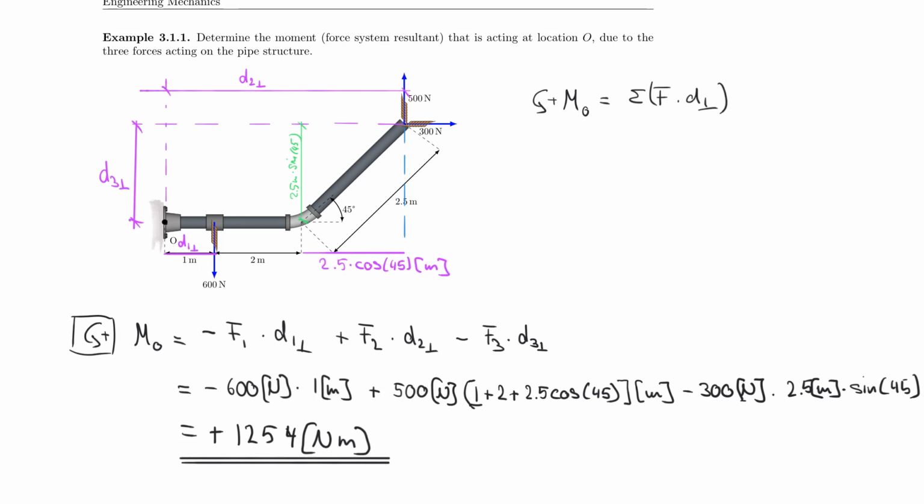And then also that we set plus here, because the plus tells us more than just it's a positive number. It also tells us that we're dealing with a counterclockwise moment. And that is part of my answer. I always have to identify that. So this entire line here is my answer, and therefore I provide the answer key.